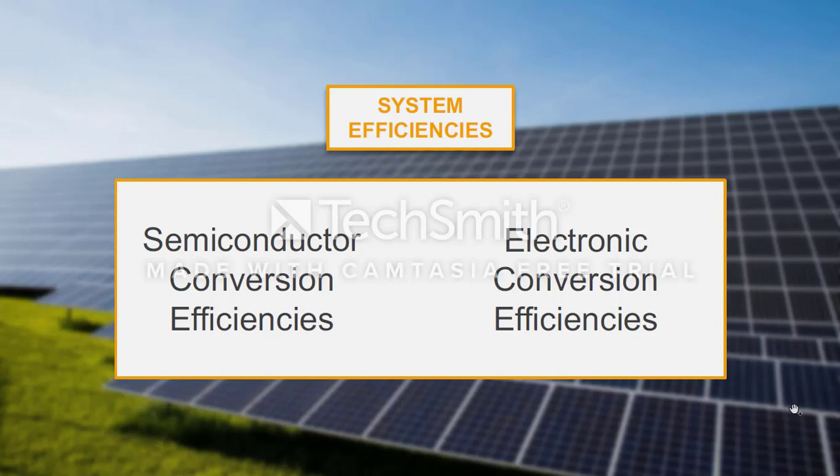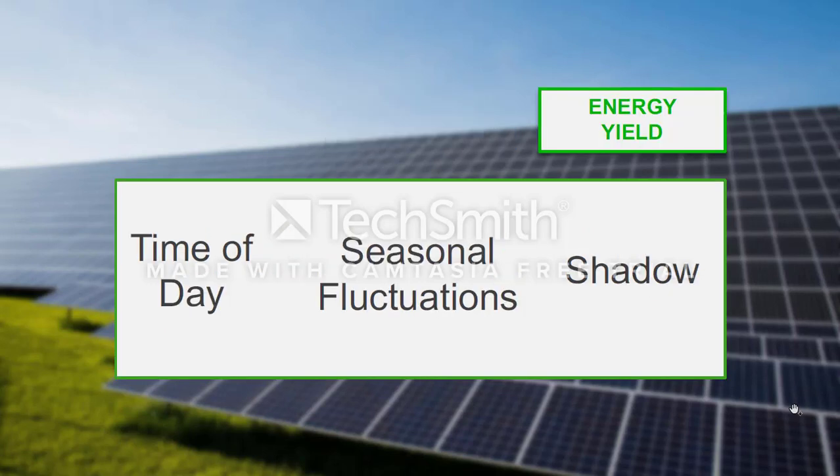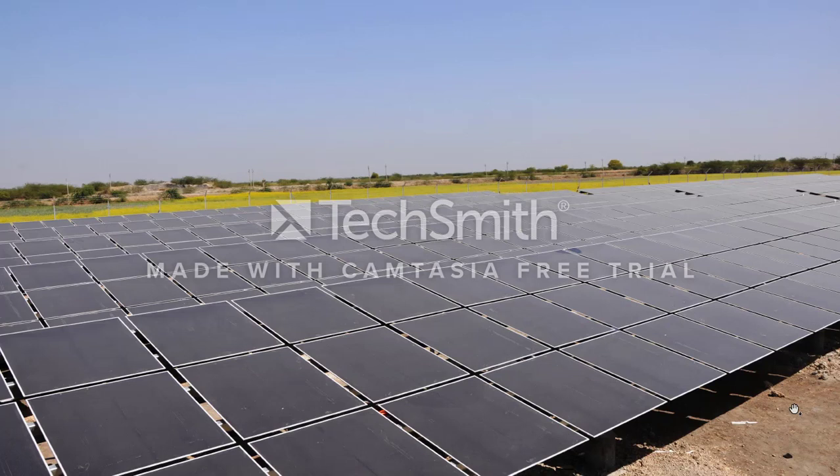Solar energy is notorious for its low capacity factor. This is because the solar radiation strongly depends upon the time of day and seasonal fluctuations. Especially in countries far from the equator, there is more sunlight available in summer than in winter. Shadow should also be considered. Some trees and buildings can cast shadows that strongly influence the performance of a solar cell. In solar farms, panels can even cast shadows onto each other. This is important when designing a solar farm.